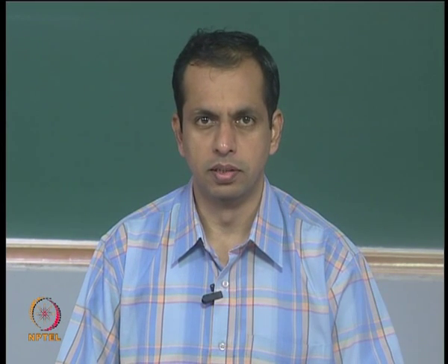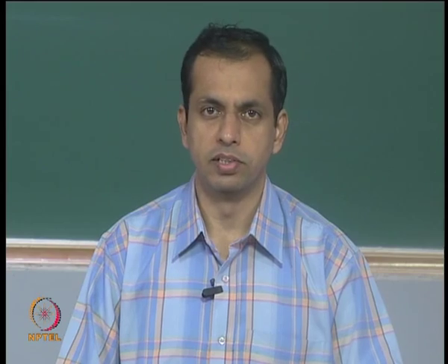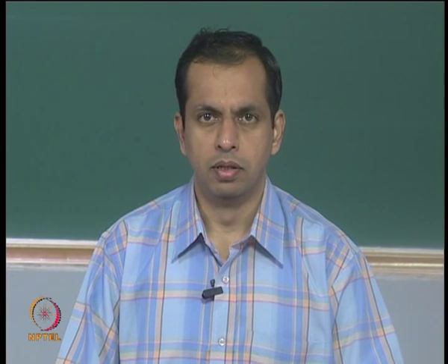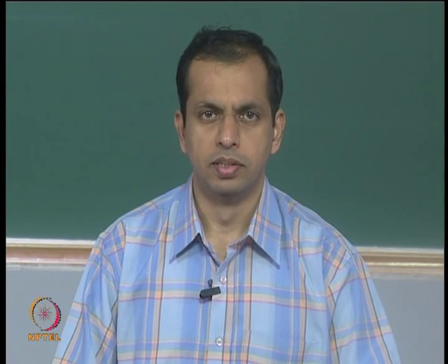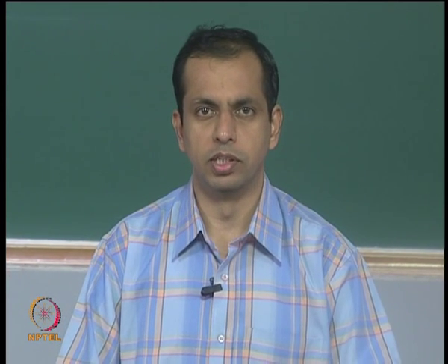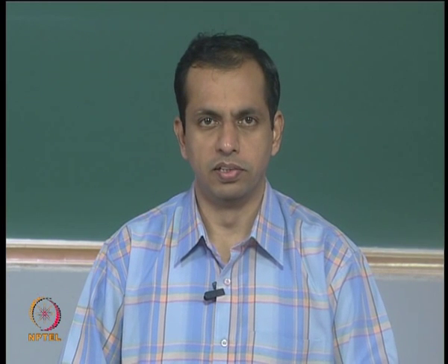Welcome to lecture 55 of analog integrated circuit design. In the previous lecture, we discussed the band gap reference in great detail. It provides a very stable voltage reference that is independent of process variations and temperature. It gives you 0 temperature coefficient at a particular temperature, so that the voltage variation over the temperature range we are interested in, that is about 0 to 100 degree C, is small enough.